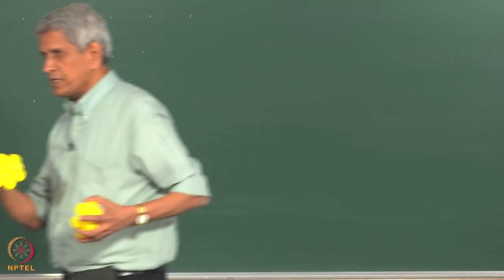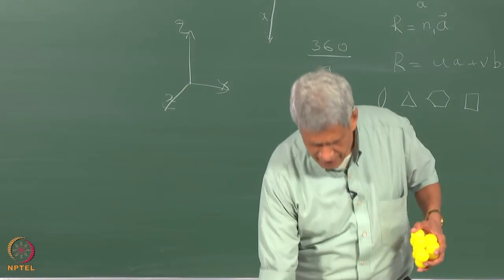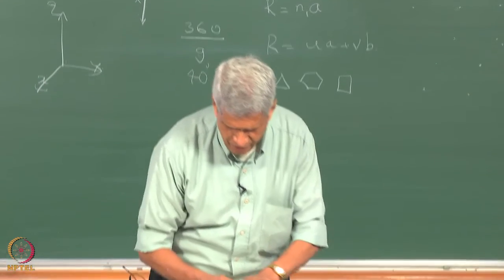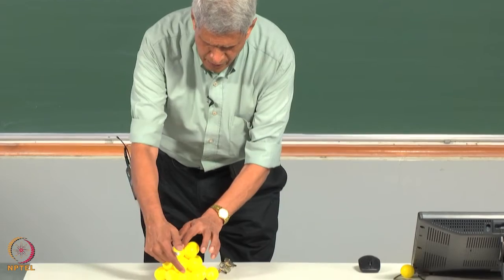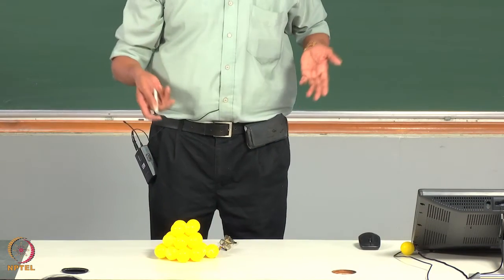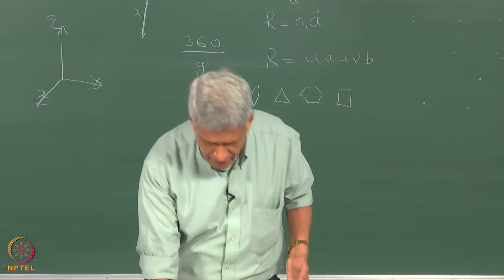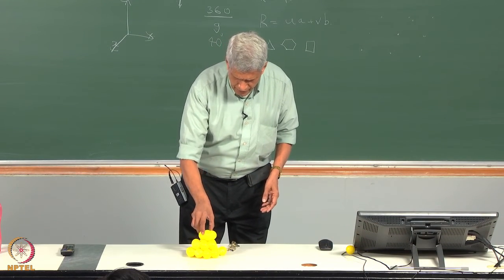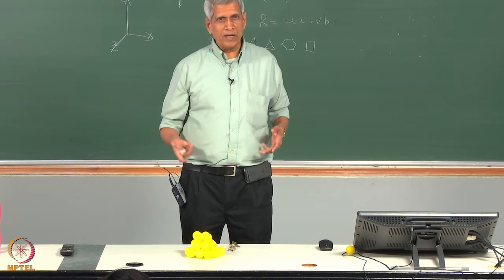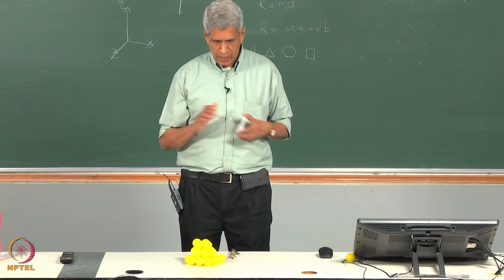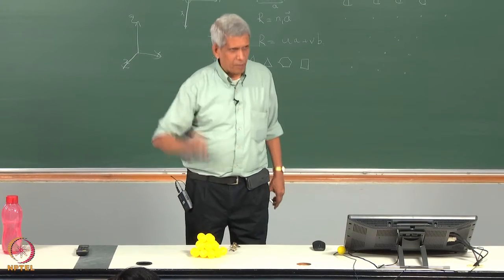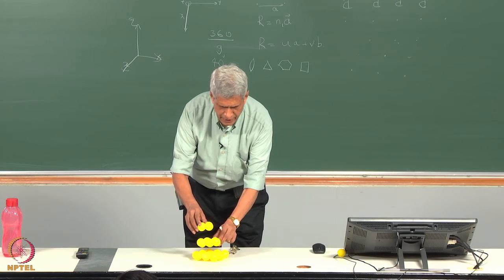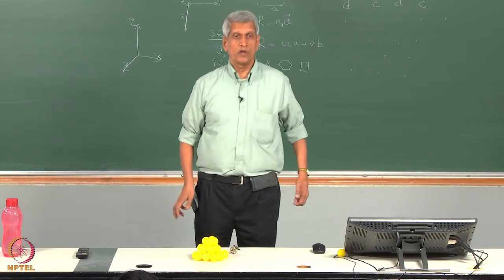Here, if you look at it, this is a hexagonal lattice, correct? In this hexagonal lattice, if I keep it at one particular A position, and this is another position which comes on top of it, and the third one, if you see, A, B and C if I keep it, now this is also an FCC lattice, a cubic lattice, correct. If I keep this in a position like this instead of here, now this becomes a hexagonal lattice. These are all only the hard sphere model which I had kept, so they are at a particular ratio. By changing this separation, instead of not touching, if I keep it like this, A, B, and C, and another, this becomes a rhombohedral.